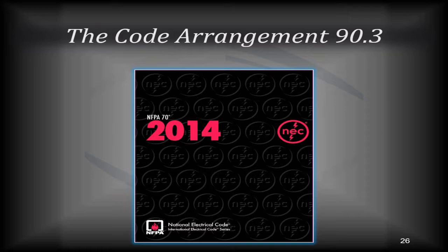For example, they give you the residential load calculation for the VA in a house. So if you look at trying to figure out lighting loads and your square footage and all that kind of stuff, just going through the NEC, it might be pretty tough to put that all together. Well, Annex D puts together in a nice couple of example calculations to show you from goose to gander how to calculate a residential home. It tells you the demand rating values, how to figure out square footage VA for the lighting load, what the small appliance circuits are supposed to be accounted for, as far as how much VA they are.